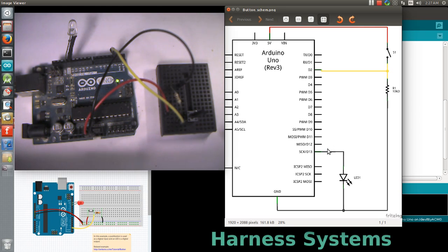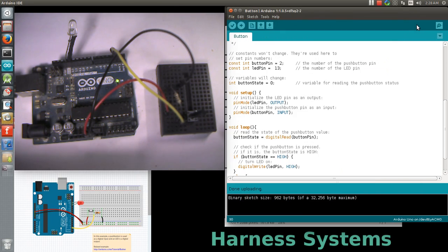Currently the circuit diagram is in active low state. When switch is turned on, then there is a closed circuit which is established between the controller and the switch, and the circuit turns to be active high. This status of switch is going to be read through our program, and based on the status we will be toggling the LED. Now let's see how that is been done in the program.